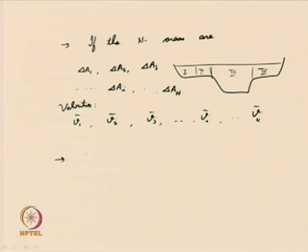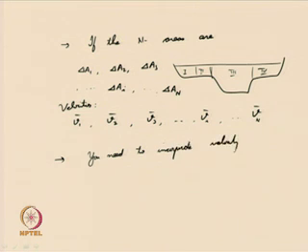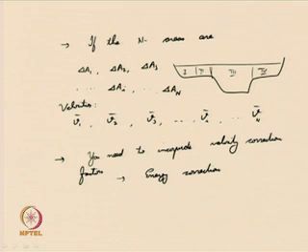So, as we mentioned earlier, you need to incorporate velocity correction factors appropriately. For example, if you are computing the total energy head, or wherever the velocity head is coming into the picture, you need to incorporate the energy correction coefficient for velocity.